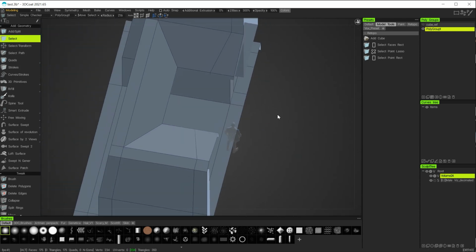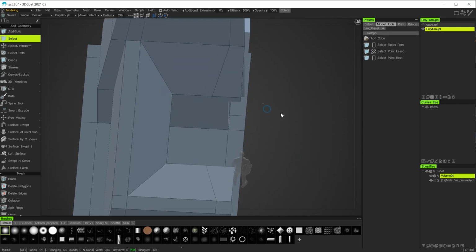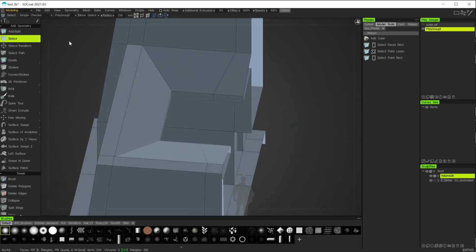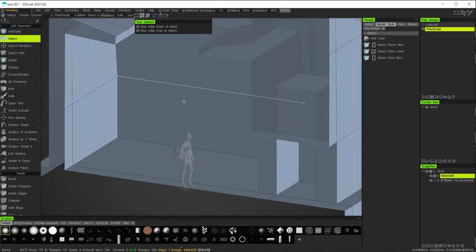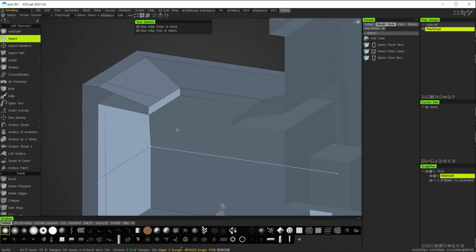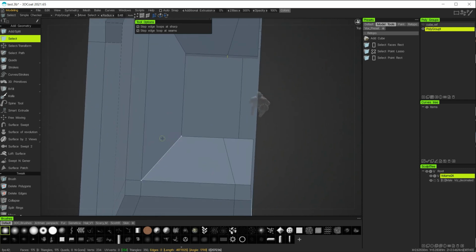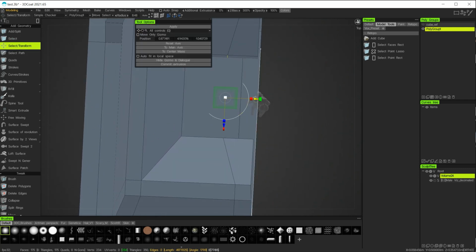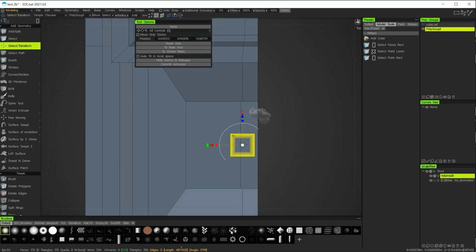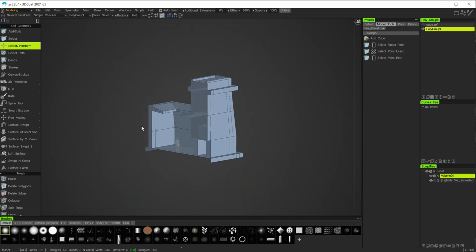Like so. I've got that weird thing there where this edge here is moving over. So let's correct that problem. So let's choose edges and select. I'm just moving the brush size down here. Select that edge there and that edge there. With those two selected, I'll select the move tool here and just move those. Snap to that view there. Just kind of straighten those two up there.